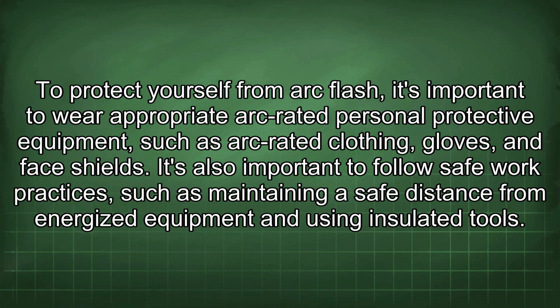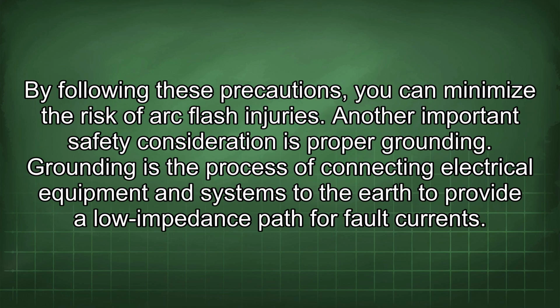It's also important to follow safe work practices, such as maintaining a safe distance from energized equipment and using insulated tools. By following these precautions, you can minimize the risk of arc flash injuries.